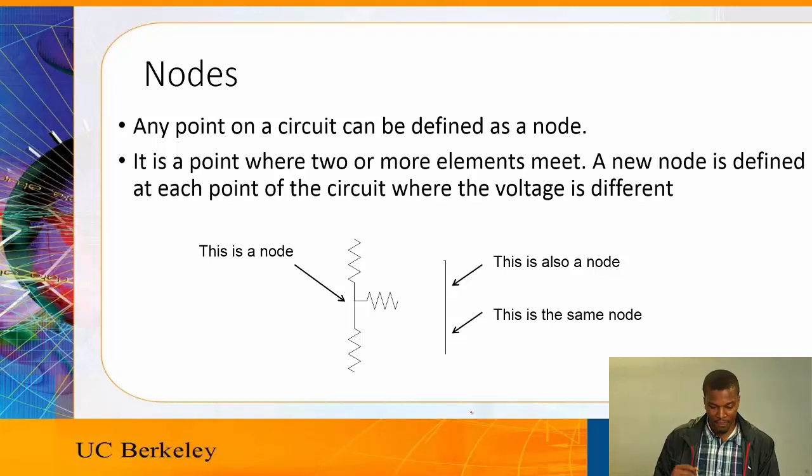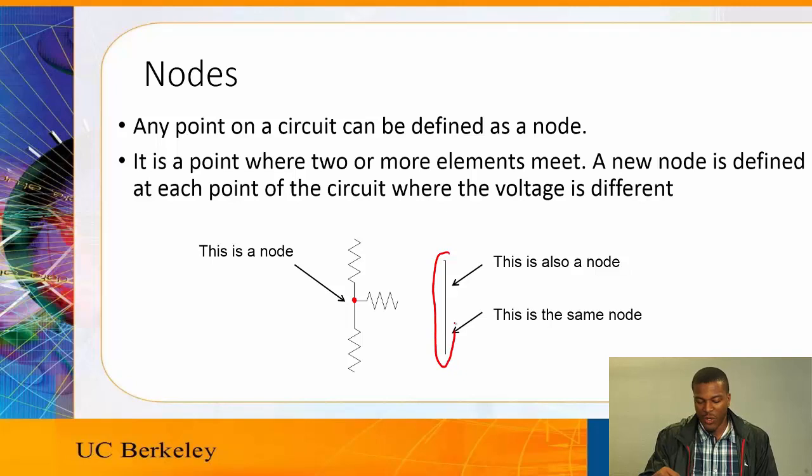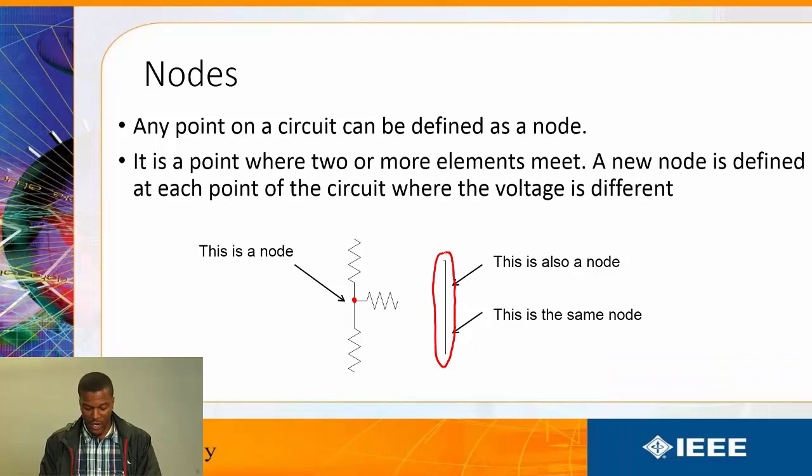than one direction. So in this first example, we can see that this point right here is a node because it's a point where more than one element meets. And this example to the right has 0 electrical elements, so the entire wire would be considered just one node. Using our understanding of nodes, we can do some pretty cool simplifications and analysis on our circuits.